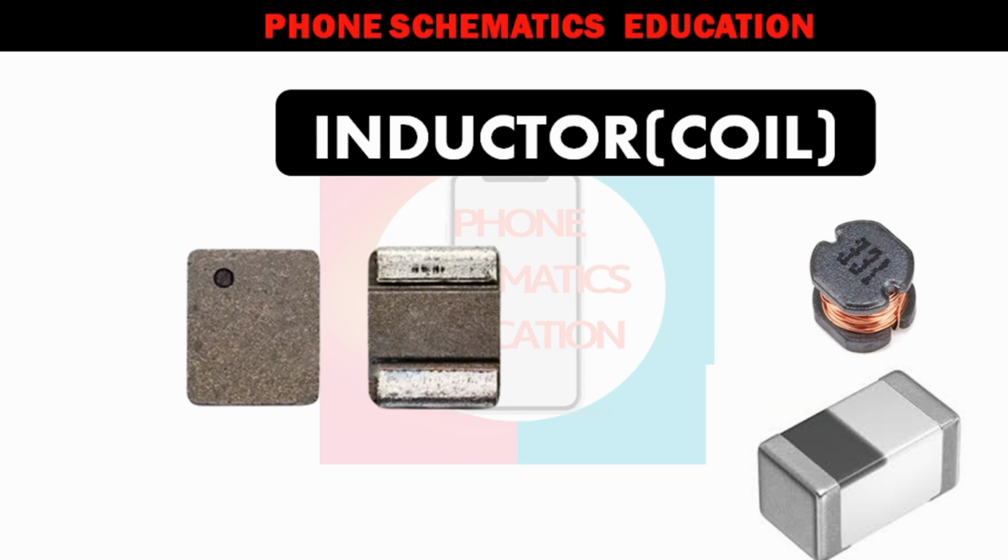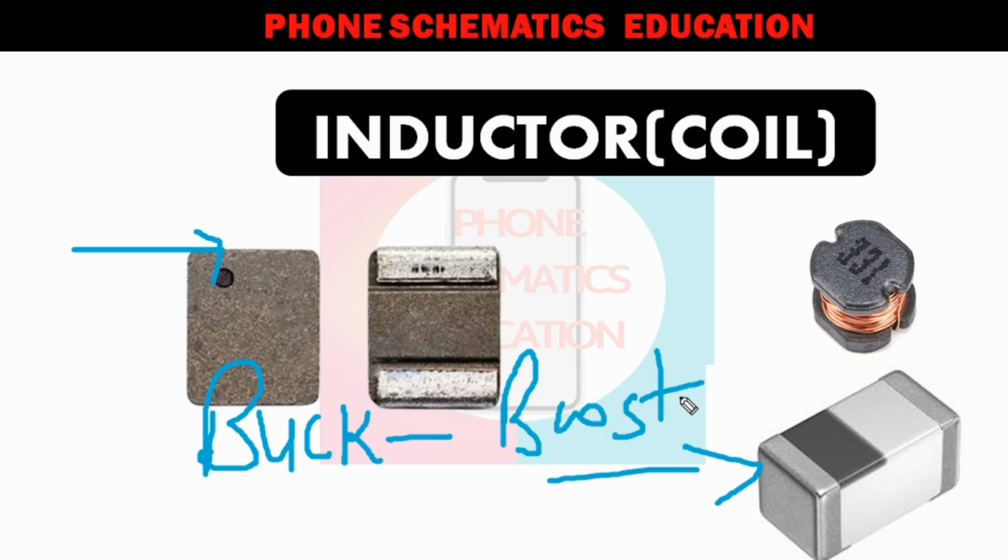Now let's get back to the mobile phone PCB. In a power section, in a network section, you will see these types of RF inductors, but I'm talking about the power sections, right? In a power section, you will see two types of coil with different shapes, right? First one buck and second boost, right? You will see these buck coils near the power IC. I've already shown you on a motherboard, right? The boost coil you will see near the light IC, also the graphic IC.